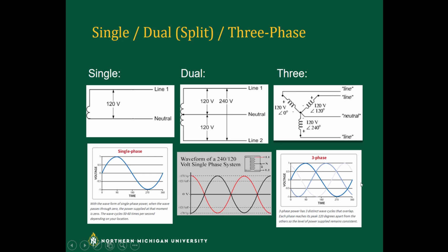It can distribute power a lot more efficiently and with a lot greater capacity. The more phases you add, the more capacity you add, but it's determined that 3 is a really good number for it, because as we start getting into, say, 6 or 9 phase power, the infrastructure requirement is so high that you're not really getting that return on efficiency that you would hope for. So 3 is sort of the number that's been settled on.